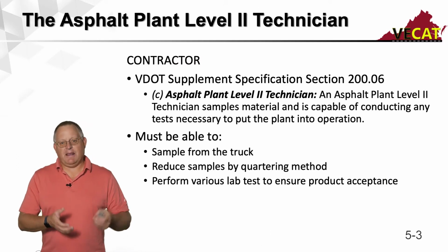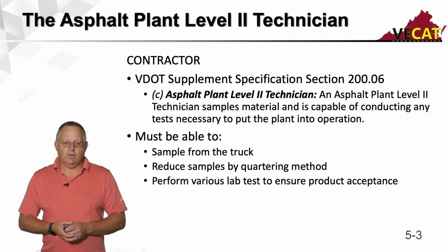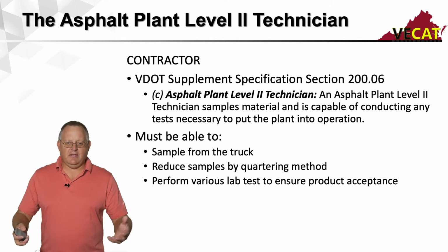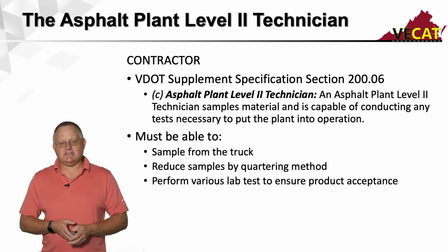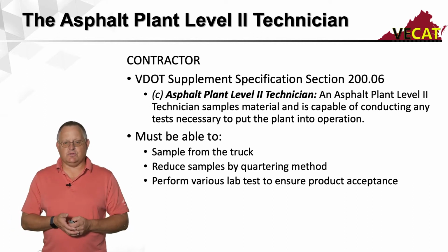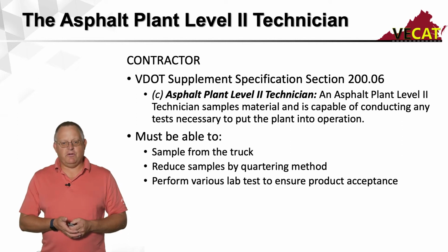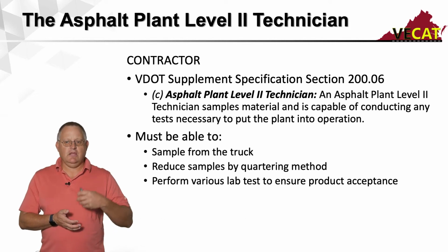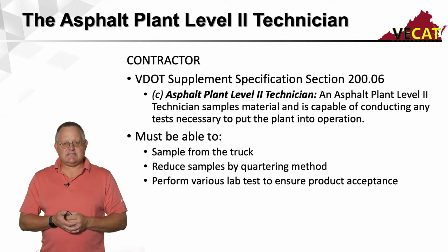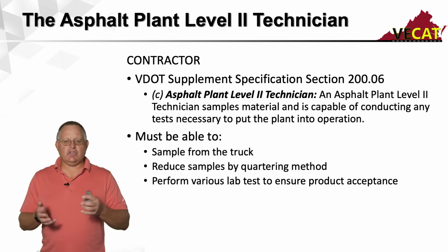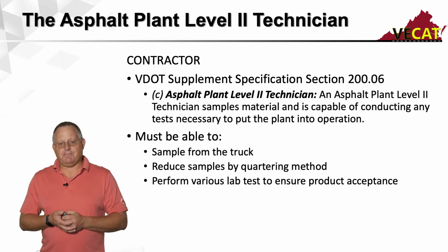What is the Plant Level 2 technician? Well, if you think about it, we have the contractor side. Where do we spell it out that we need it? Well, you've got to look in the specs themselves. In section 200 of the spec book, it lays out the materials related stuff. And if you actually look in 200.06, it clearly defines what that asphalt Plant Level 2 technician must be able to do. You're doing any of the tests necessary to put the plant in action. You're not changing mix designs, you're not adjusting them, but you're putting that plant into operation.